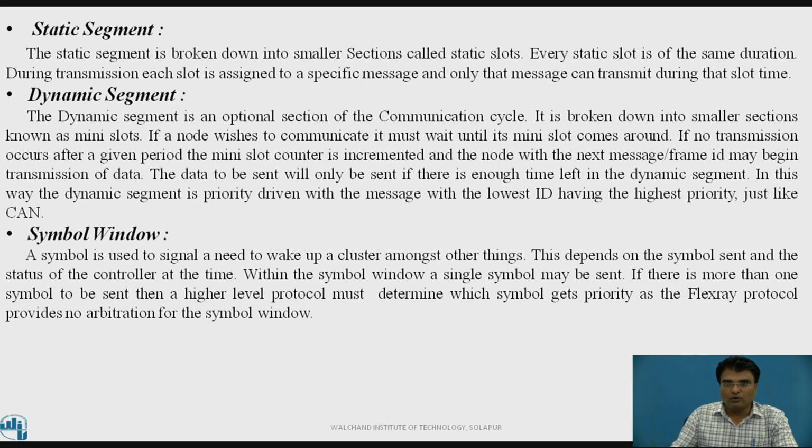Within the symbol window, a single symbol may be sent. If there is more than one symbol to be sent, then a higher level protocol must determine which symbol gets priority, as the FlexRay protocol provides no arbitration for the symbol window.